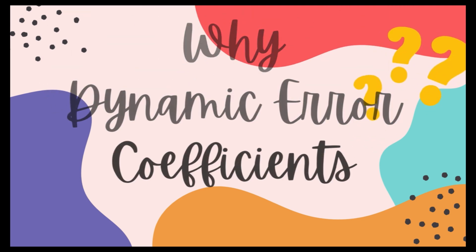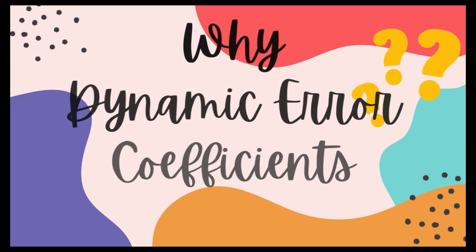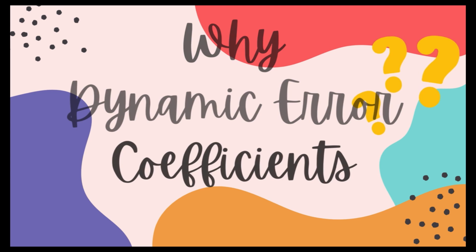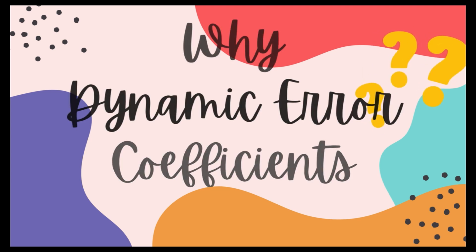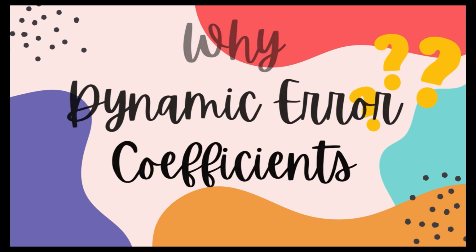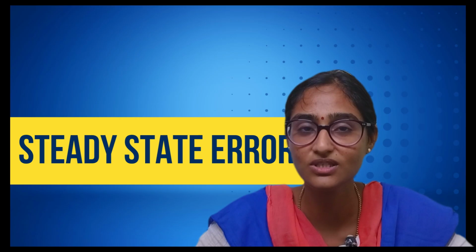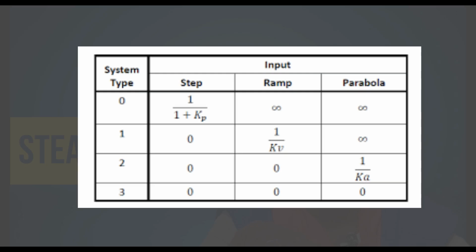Because we know how to find the static error constants against different test signals and against different types of systems too. So we can quickly find the steady state error just with static error coefficients, right? Why do we need to go for dynamic error coefficients? This is because for some of the inputs we get 0 or infinity as the error, though we practically know there is no zero error or even infinite error for that matter.